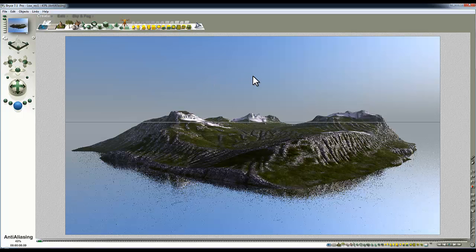So there you go. That's one approach to overcoming the problems that are inherent from using the curvature filter. Even though the mesh smoothing issue could be overcome by correcting that in Bryce, you'd still have this transitional problem where the interpretation of what is convex and what is concave becomes confused when you've got another plane involved. So if you're just looking along one axis, then it's easy to tell whether you're looking at a convex or a concave surface. But when you introduce another axis, I know the perfect example: a saddle shape.